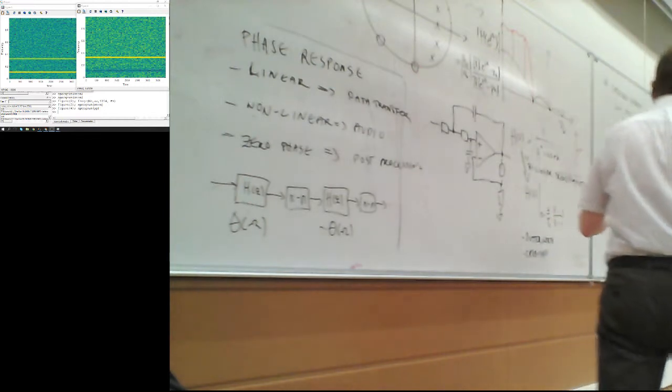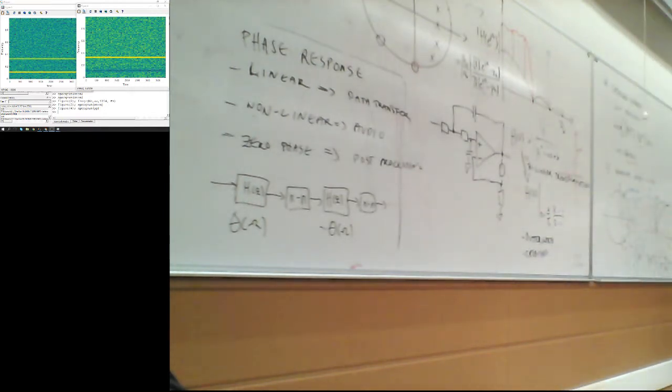And also to tune. So if you had a spectral analyzer on a system which is basically maybe a digital phase lock loop following what is this exact frequency, then you could basically make an adaptive filter which follows this 440 hertz signal plus minus something. But that's again advanced topic, not part of this course.